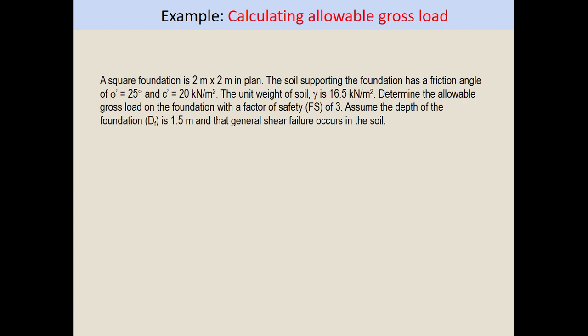So this is the example: calculating the allowable gross load. You see here, the question asks you for the allowable, which means the design load that we allow. So allowable means the load, capital Q. A square foundation means you can use the Terzaghi equation.